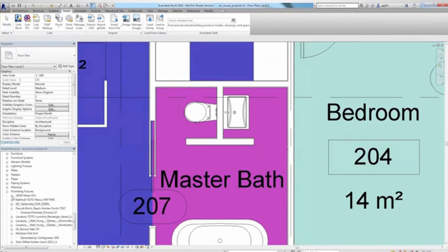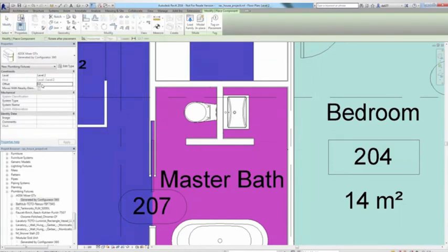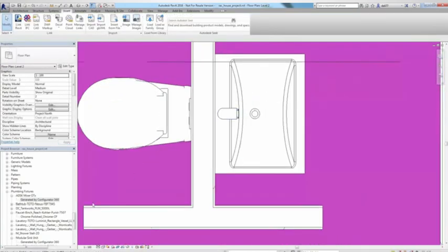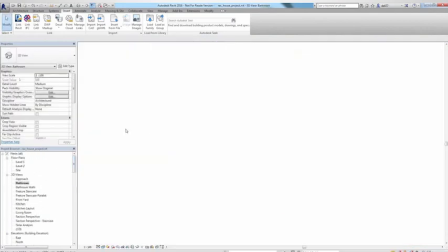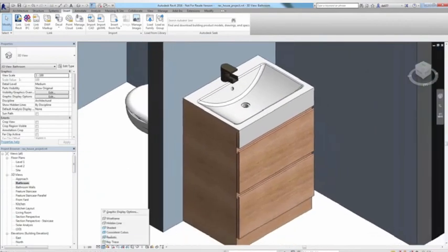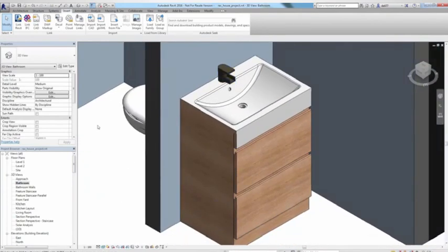So the architect looking at your product range, they can choose what they want, and then once they've chosen that, they can download that as a Revit compatible file, be it a Revit file or an IFC file if it's going to another architectural product other than Revit. Once that's done, it's the same process as you saw with the staircase or with the air conditioning unit, where I bring that in, I load the family, and then just place it on the basin in this case. And then that's part of my architectural design. Once again, the prime point here is that it's got all the detail embedded inside of it from a BIM perspective, because we've added that manufacturing content, okay, with metadata.